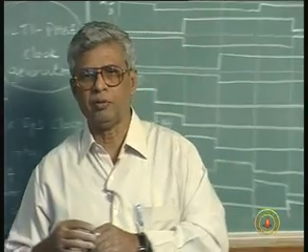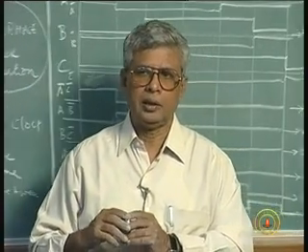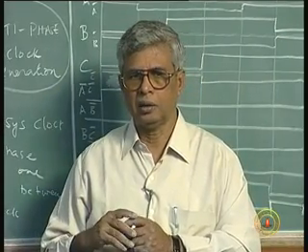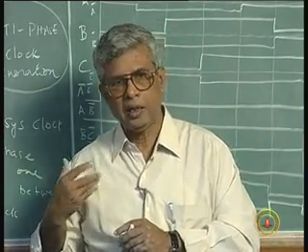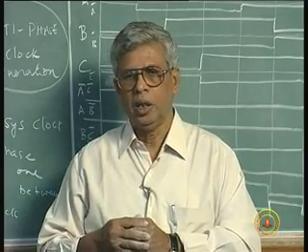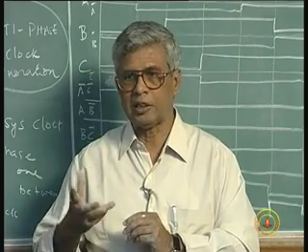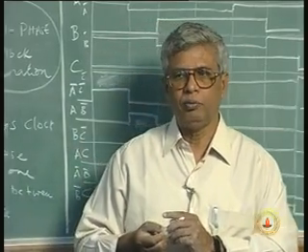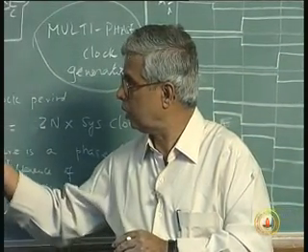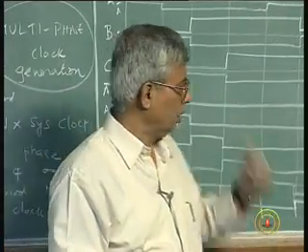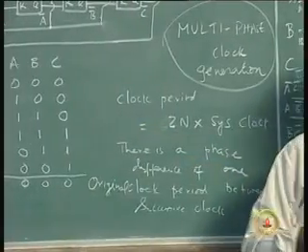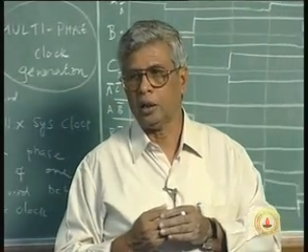These are all building blocks of digital circuits. First we saw combinational building blocks, gates, adders and all that. We saw then sequential building blocks, flip flops. Using flip flops we saw how to build counters and how to build registers, how to build shift registers, and shift register is a very frequently used component in many digital systems. I have given you some applications today, the pseudo random sequence generator, the Johnson's counter, and then the parallel to serial, serial to parallel we talked about the other day and all that.